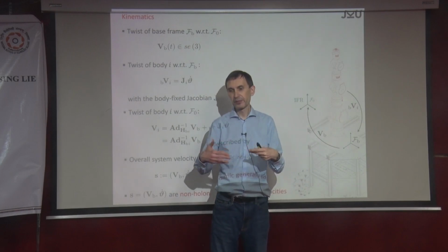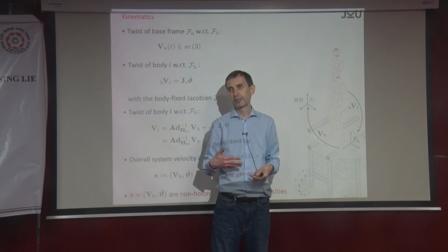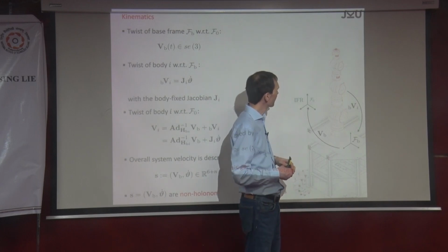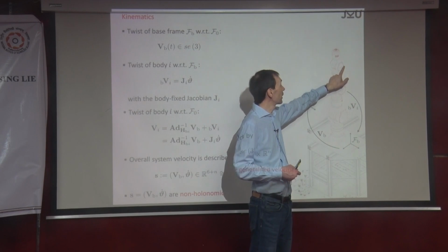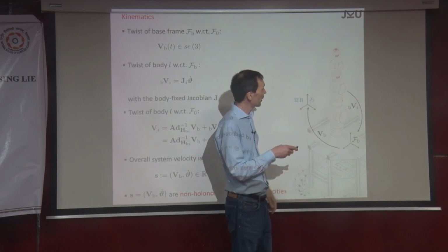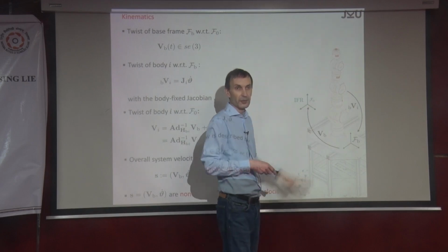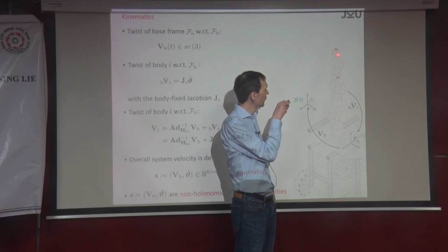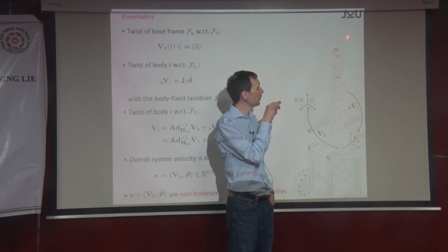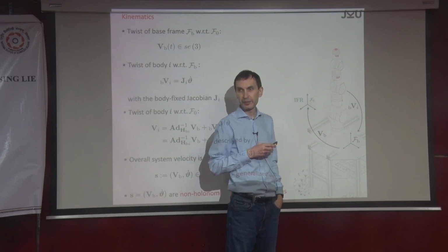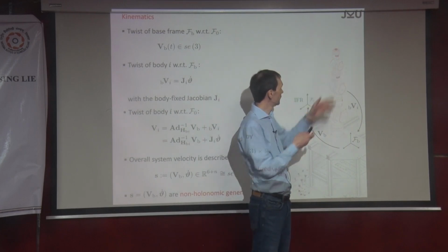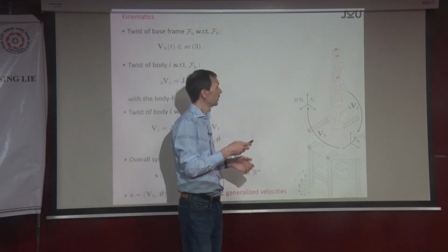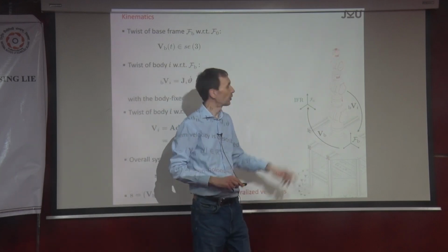In a sense, you want to feel in your motor current the effect of the inertia. Look at the last link. Let's say you are rotating about this axis, and only the last one. What you are probably able to get is the mass and inertia, and maybe even the center of mass of the last link. Because if you're turning here, the torque that you need is certainly related to the mass and the inertia of this last link.